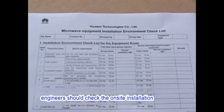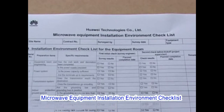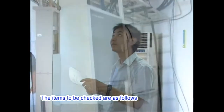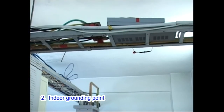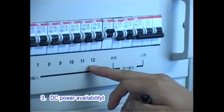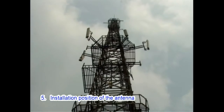Before installation, engineers should check the on-site installation conditions according to the Microwave Equipment Installation Environment Checklist. The items to be checked are as follows. 1. Installation position of the IDU. 2. Indoor grounding point. 3. DC power availability. 4. Environment temperature. 5. Installation position of the antenna.